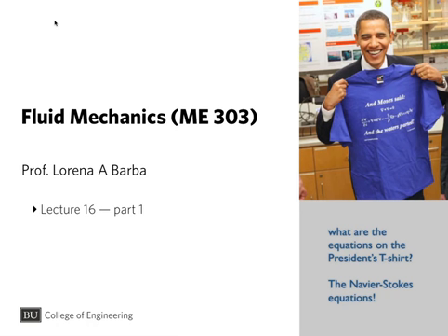We were discussing Reynolds number and the importance of Reynolds number, and we said it represents the ratio between inertia and viscous effects. And so we discussed a little bit what it means to have inertia and viscous effects competing to dominate in a flow. And we saw some movies there to illustrate this idea of inertia and viscous effects. Then we said, well, if you go to really, really low Reynolds number, you have what's called the creeping flow. In really, really low Reynolds number, the Navier-Stokes equation simplifies quite a bit, basically because